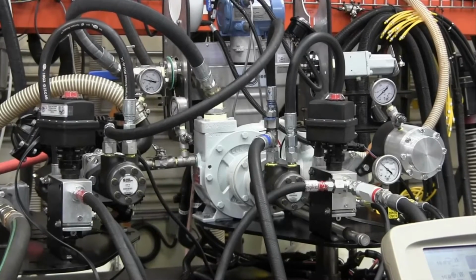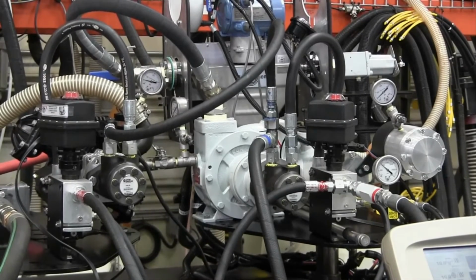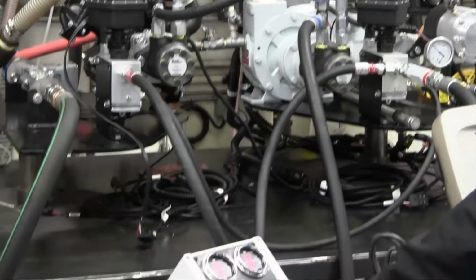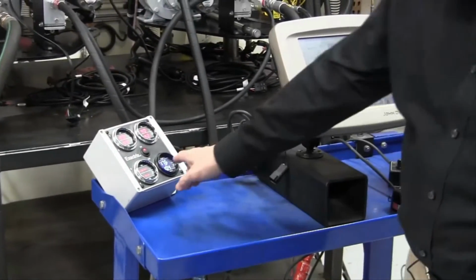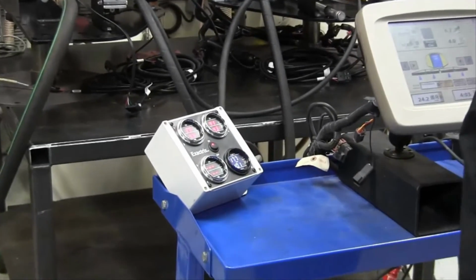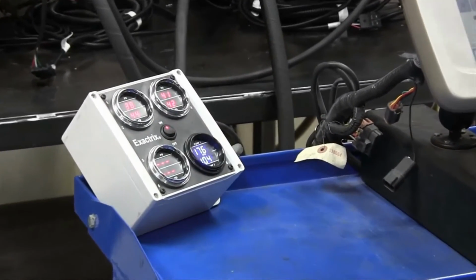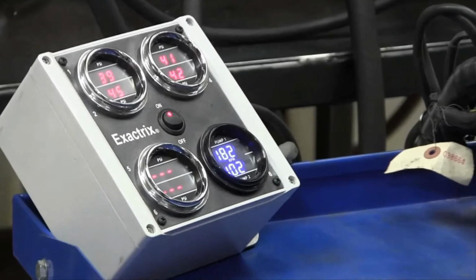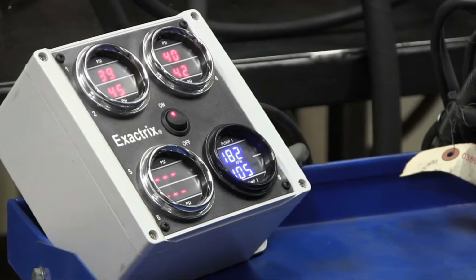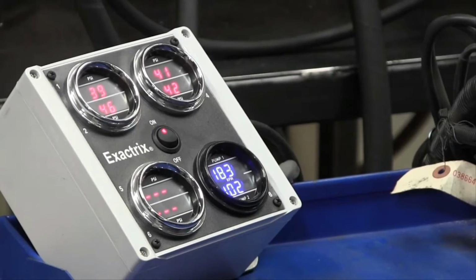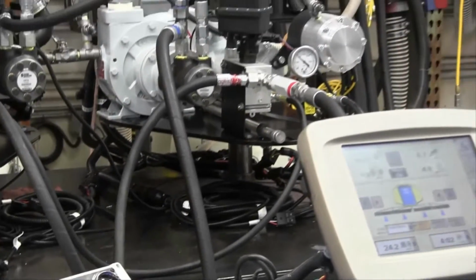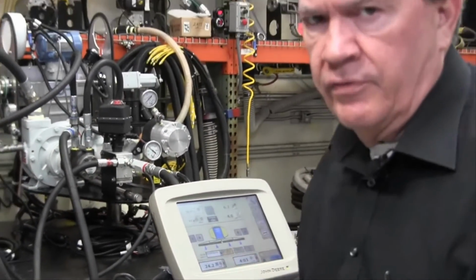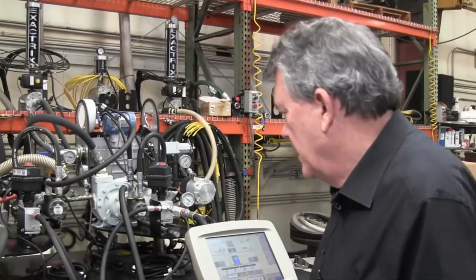Now this is at 7 miles an hour and we have dialed in a 10-gallon rate on the liquid pump, and we've dialed in a 150-pound rate on the NH3 pump. Of course, in practice the NH3 pump will be turning about 100 RPM faster to reach 150 because it has the boost to the tank. So we're running primarily water through the system right now.